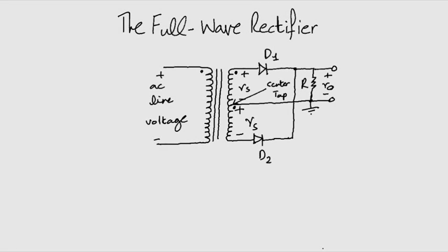The full wave rectifier produces output peaks for both cycles. All the peaks are positive. Consider this circuit. This is one implementation of a full wave rectifier. The secondary winding of the transformer is center tapped. Hence, two equal voltages are provided to each half.